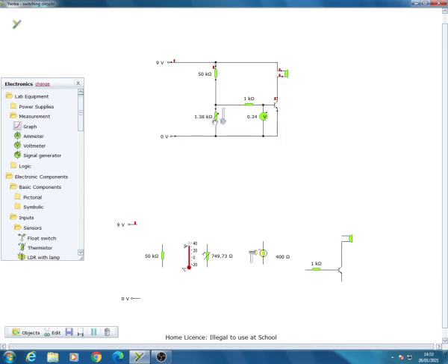As I increase the resistance down here, what happens is that less of this 9 volts disappears over there. So I'm now dropping 8 and a bit volts over here, and I'm dropping 0.2 volts over this bit. Now that bit you don't have to remember or know at the moment. We can do some more work on that.